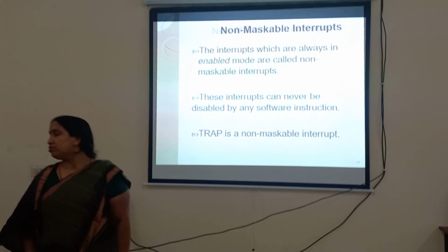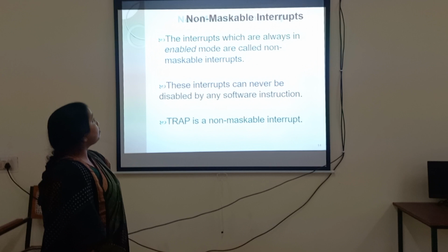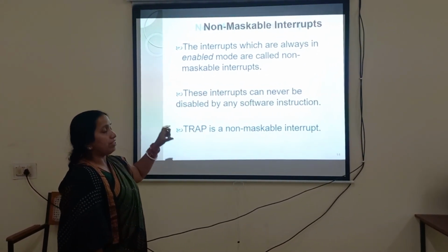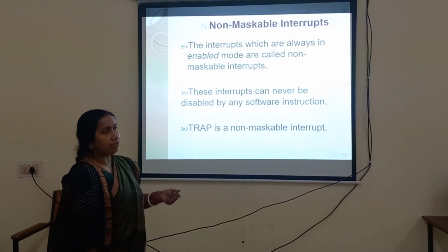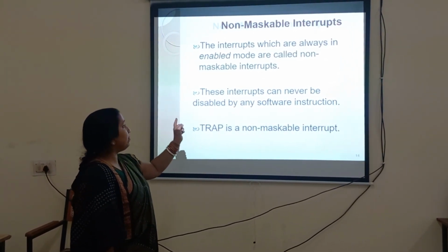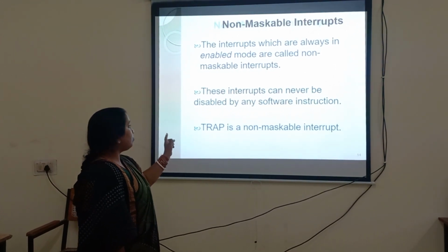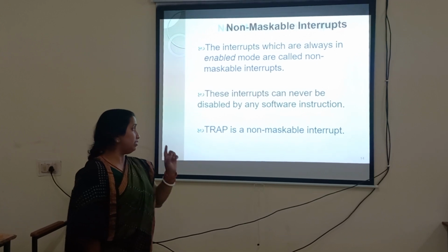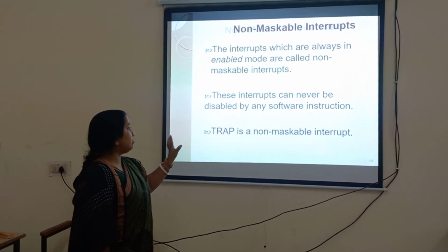The next slide shows the non-maskable interrupts, which are always in enabled mode, that means they are enabled by the system only. We cannot manipulate this. These interrupts can never be disabled by any software instruction. So TRAP is a non-maskable interrupt. Only one non-maskable interrupt is there, that is TRAP.